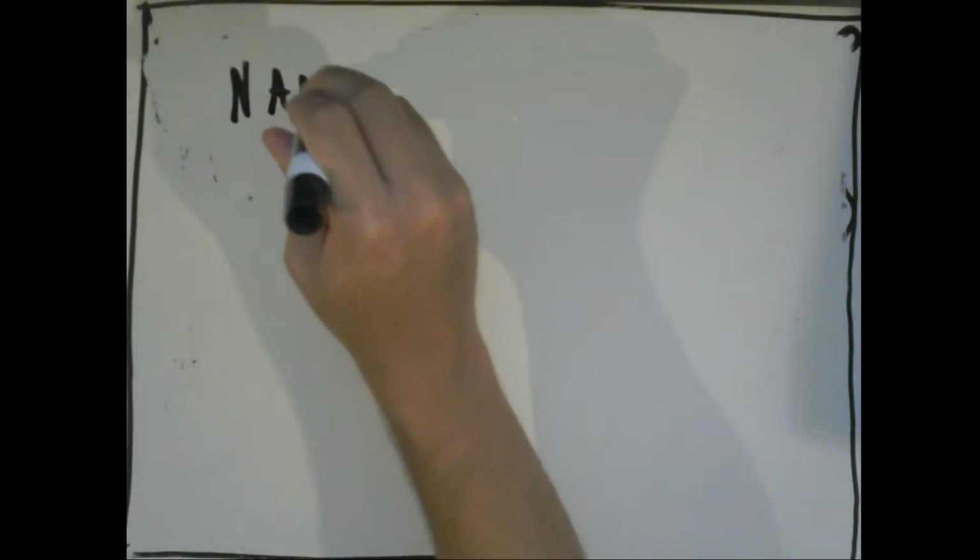So I'm assuming you guys might need to do something like you have an equation and you need to convert all the terms in your equation to NAND or NOR gates. So let's talk a little bit about that. NANDs and NORs are interesting because they're logic complete, which means that you can form any equation using only NANDs and NORs. So let's write some NAND gate equivalences.